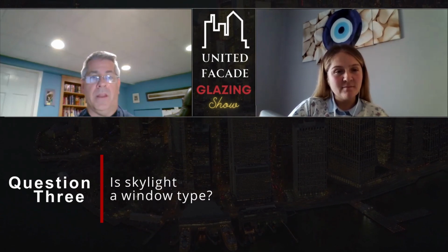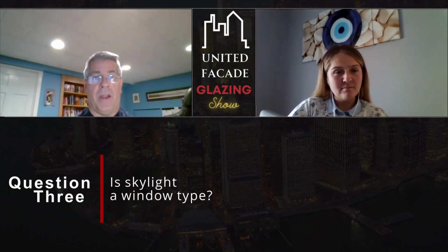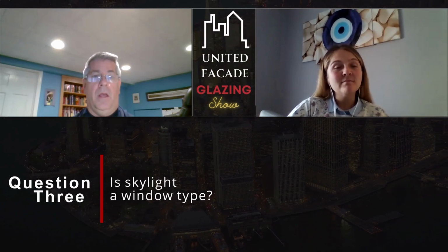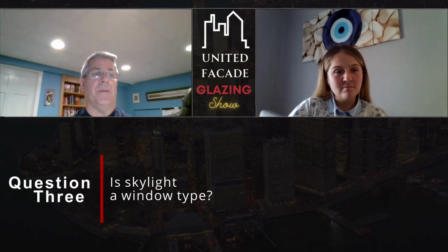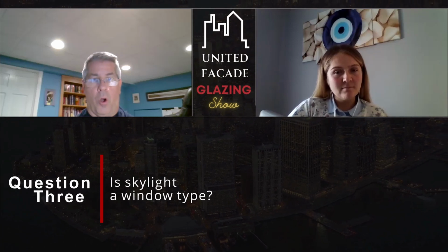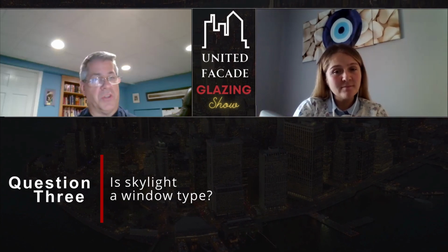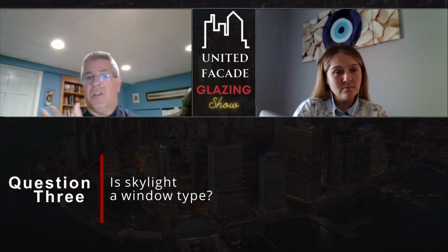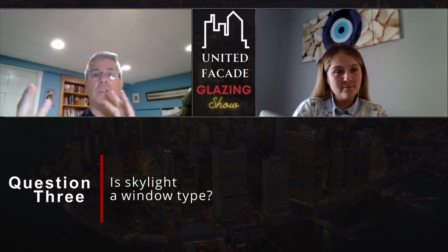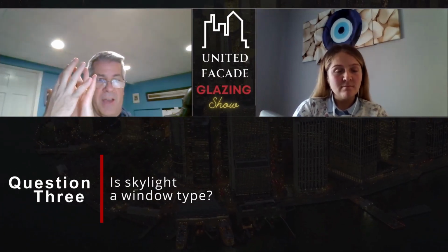It's required, at least in the New York City area, to have laminated glass inside of a skylight. The reason for this is, picture the windshield of your car. Unfortunately, I'm sure we've all seen, either in a movie or somewhere, that if something hits the windshield, it breaks and shatters, but all the glass stays together.